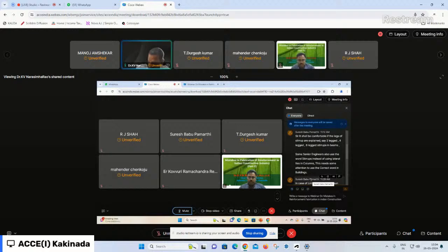the full development length. When coming to the top end being a prop condition, in the case of a prop condition, we are only transferring the vertical loads. It is something like a simply supported edge. There is no moment transfer. For that also, you should not anchor much more beyond Ld/3. If you are anchoring much beyond Ld/3, there is a partial restraint. If you are embedding up to full development length, there is full fixity.